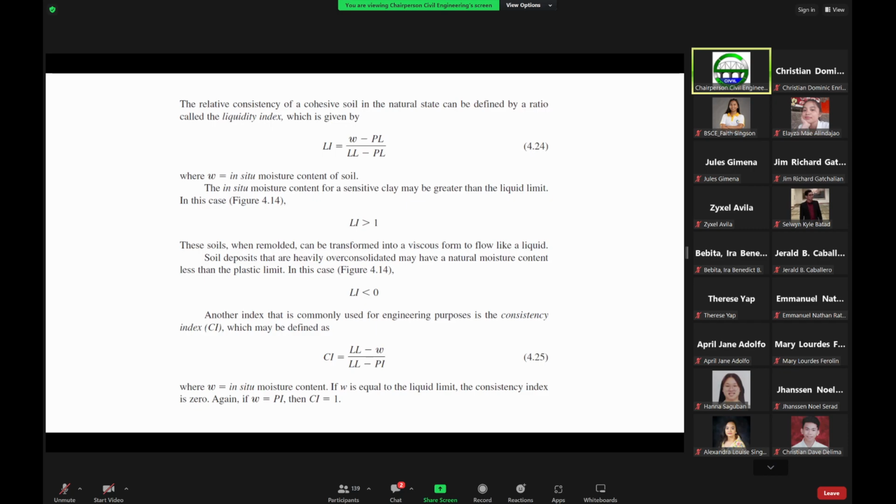In our case, we normally use automatic drilling rigs, which are a bit more accurate, and we also use automatic water level recorders, which we drop into the borehole to measure the groundwater levels for that particular site. Because again, the problematic soils, such as the collapsible soils, the expansive soils, and the liquefiable soils, are a function of the groundwater level.